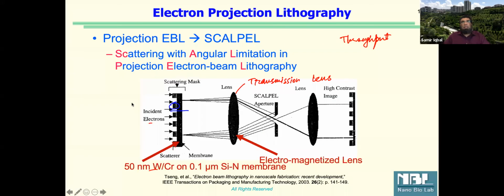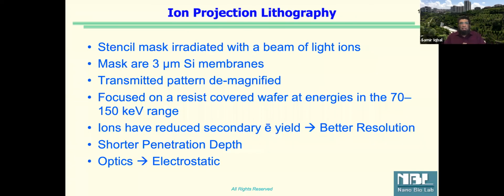So the way we are doing electron projection lithography, so you see the word, instead of using electron beam lithography, now we say electron projection lithography. So instead of using one beam, we are projecting bigger beam and using a mask with it. Are you with me on this idea? Thumbs up, down? All right, very good.